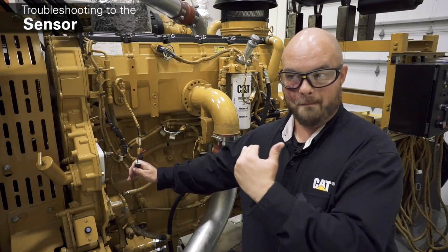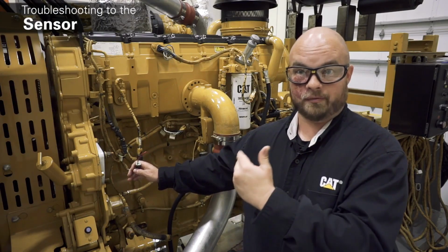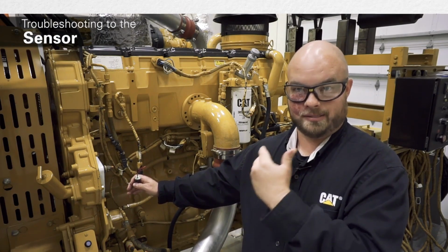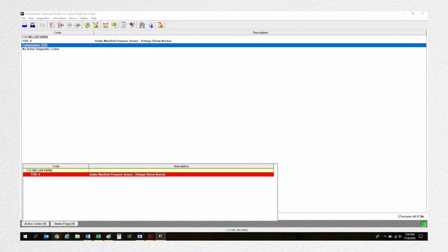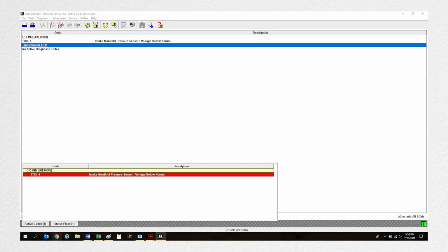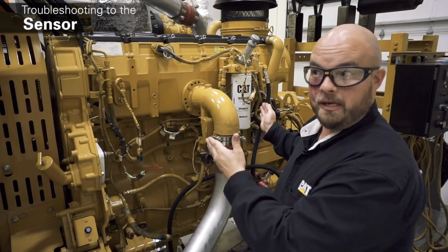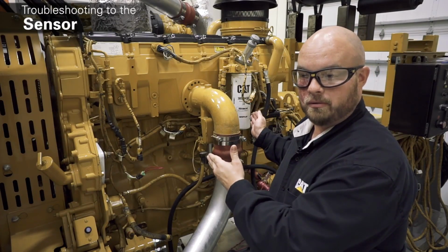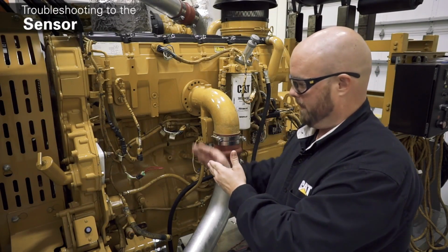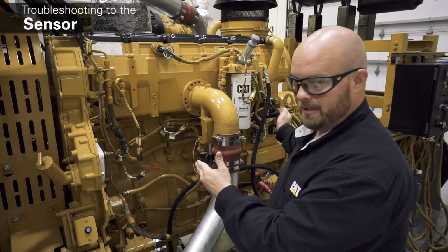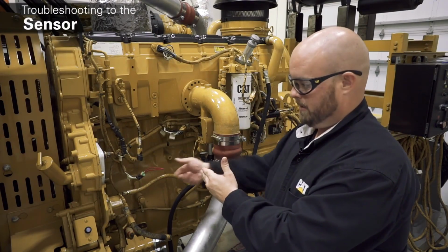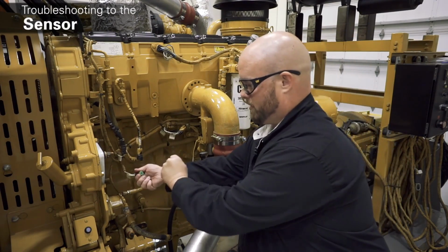Okay, so I've made a short circuit. If the ECM then at this point tells me that it's seeing a -4 short circuit condition, voltage below normal, okay, what does that mean? I made a short here. From this point all the way back to the ECM, it's doing what I expect it to do. So let's think about that. I have a short, the ECM tells me I have a short. I remove my short circuit.